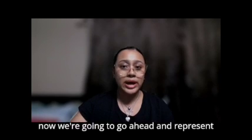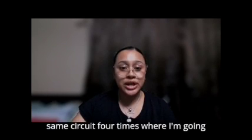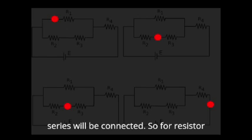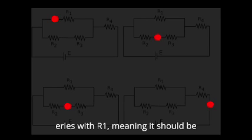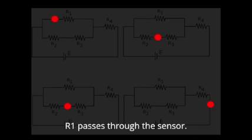So now I'm going to go ahead and present the diagram labeling explanation. Here you're going to see the same circuit 4 times, where I'm going to be presenting where the sensor in series will be connected. For resistor 1, we place the current sensor in series with R1, meaning it should be connected directly along the path before or after R1, so all current through R1 passes through the sensor.